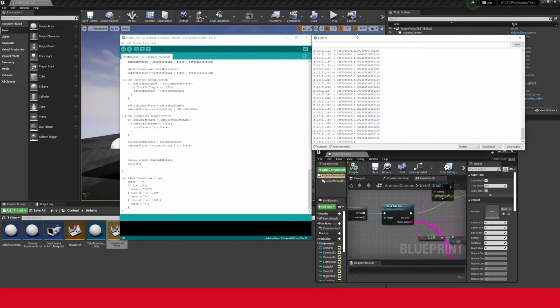And the first value is the left potentiometer. You can see that's changing as I go up. The limit is supposed to be 1023. Not quite hitting that. Right down to 0. And then the next block, so if I put this at top value, you can see 0503. That is the X value of the joystick, which ranges between 0 and 1023. And then the next slot is up and down, so Y, 1023, 0.